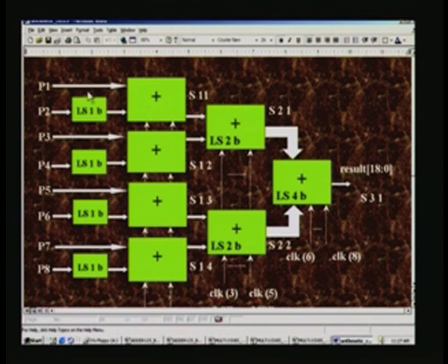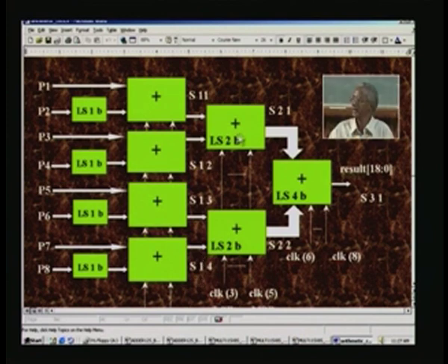What we have seen is the total number is bifurcated into two, roughly half. One half we call LSB, the other half we call MSB. So we add only the LSB here, and a carry will result, which will add with the MSB of these two at the second clock, and then we concatenate the two to make one complete S11 sum there.